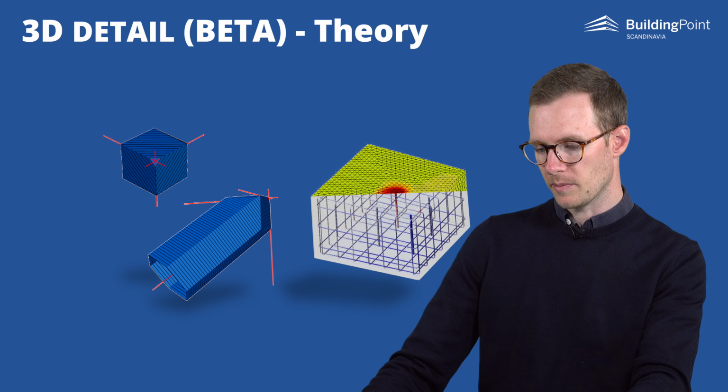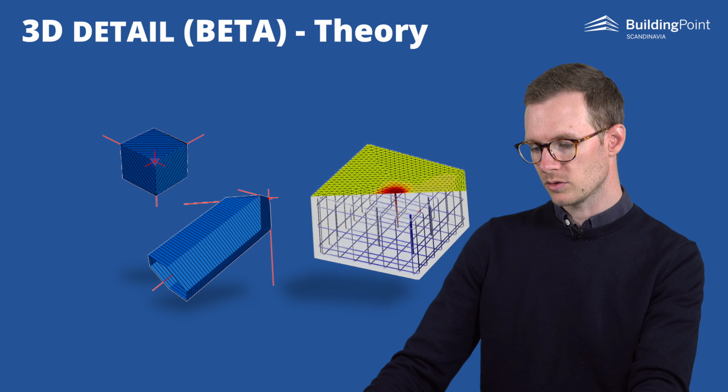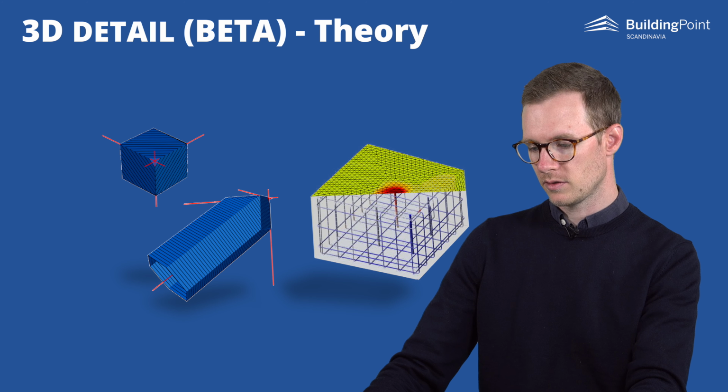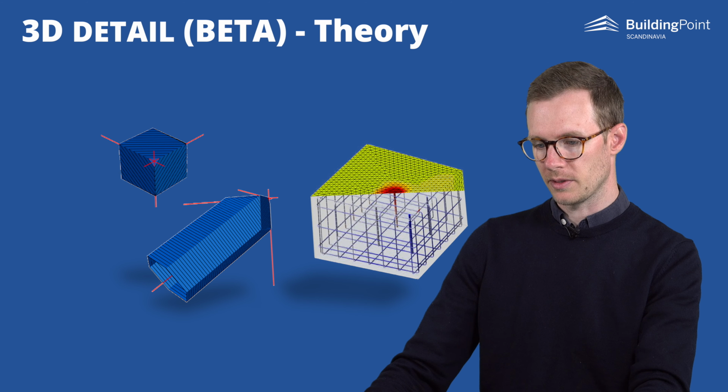3D CSFM assumes a zero angle of internal friction, leading to a conservative design due to the plasticity surface, resembling the CSFM model, which is independent of the first stress invariant.